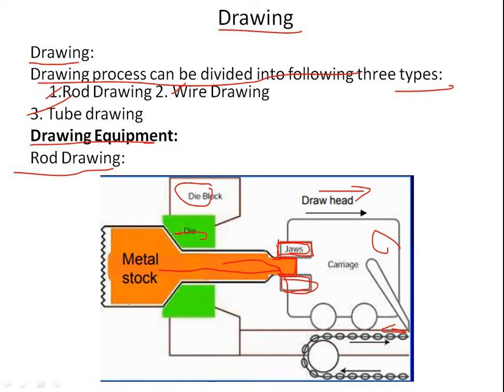So in this equipment, the rod drawing process involves cleaning the material, pointing or tagging the rod, and drawing, and these are the points. So what is cleaning before drawing? For steel rods that are previously hot rolled or extruded, surface cleaning is required.